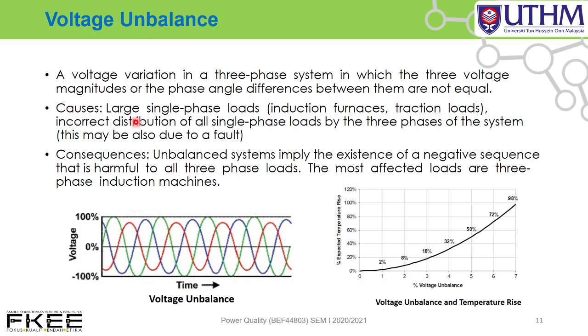It is caused by large single phase loads, such as induction furnaces, traction loads, and incorrect distribution of single phase loads among the three phases of the system. Let's say you have phase A, phase B, and phase C. Maybe in phase A you have a very large single phase load connected, which is not balanced.